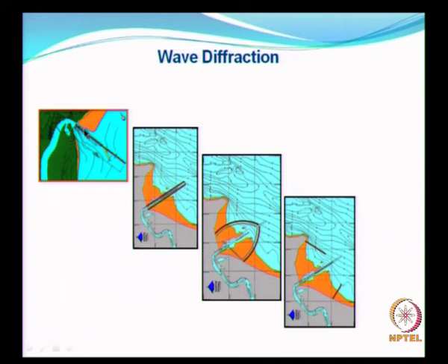So, can we have only one single breakwater, or can we go in for two breakwaters like this, allowing the vessels to move into this? Then you try to find out the diffraction through the breakwaters and try to arrive at the wave energy. Or, because you want to have some more area for this, can we have two curved breakwaters like this, or can we have two breakwaters as shown here? So for a given location you have different kinds of configuration which you can examine.